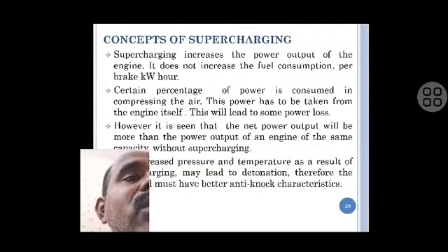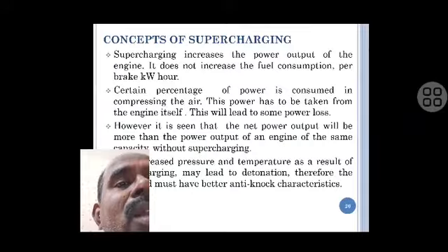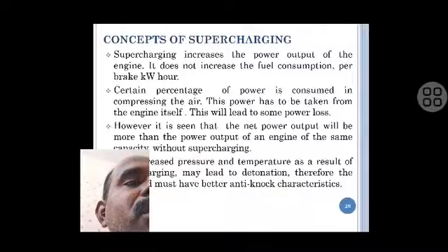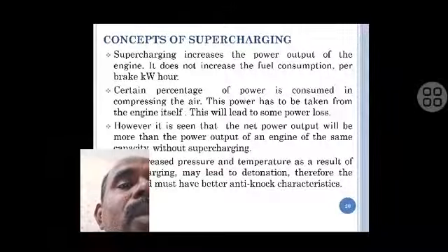The supercharging increases the power output of the engine. It does not increase the fuel consumption per brake kilowatt hour, it only increases the power output. A certain percentage of power is consumed to compress the air. This power has to be taken from the engine itself, which leads to some power losses. The net power output will still be more than the power output of an engine of the same capacity without supercharging.